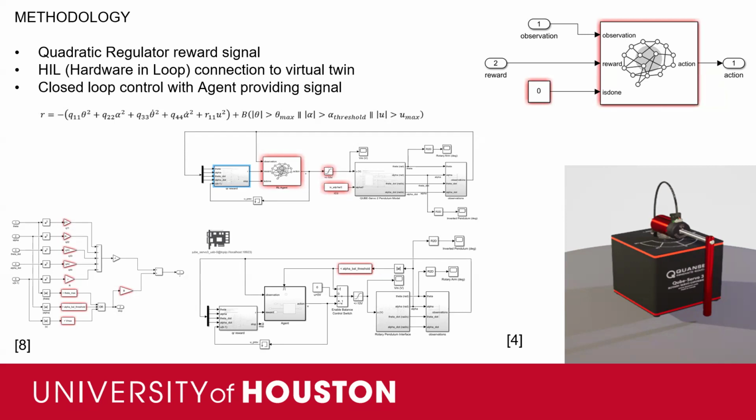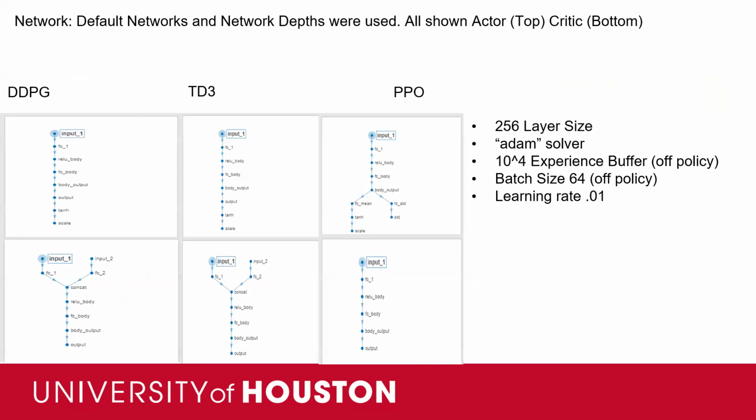Something that's real important and relevant to our simulations, we did not want the rotary arm to allow this thing to cross its own wire bundle. So all those terms are attached to a penalty factor that's part of the reward function. Now, that penalty factor can also additionally be tied to stop training criteria to locally stop the episode of the training session if you get that undesired behavior.